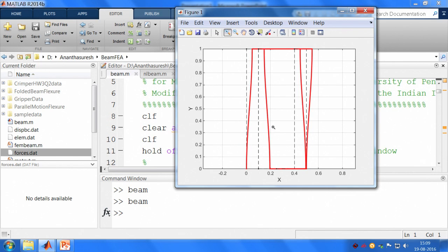But what we learnt now is, if you have finite element analysis code with you, you can generate the lumped stiffness matrix for any rigid segment that you have, or even a point. At that point, how does it feel in x, y and z directions. So, you get the cross axis stiffnesses also as part of this. What you have to do is 3 finite element analyses in 2D and 6 in 3D, because in 3D you have 3 translations and 3 rotations, all of that you can get.